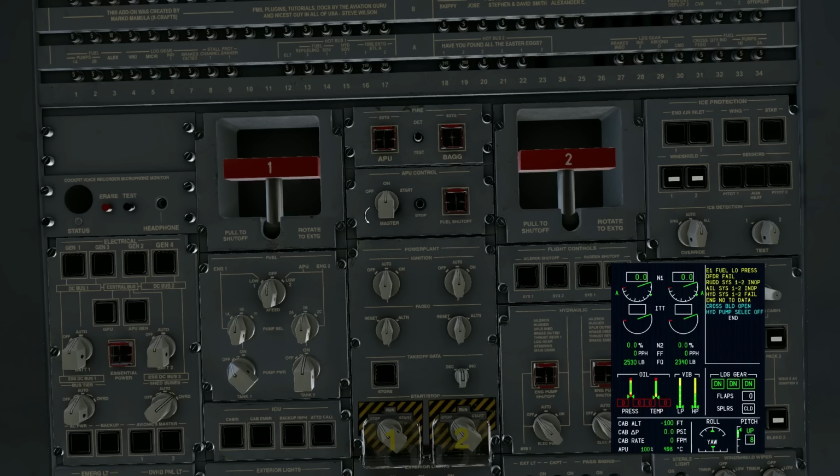And then remember that this master controller, I think of it a little bit more like the FADEC computer controller for the APU. The APU is monitoring itself for a whole bunch of conditions like an overvoltage or an overspeed, things like that, a fire indication. It's going to shut itself down for about 15 things, and then a whole list of things it'll do in the air.